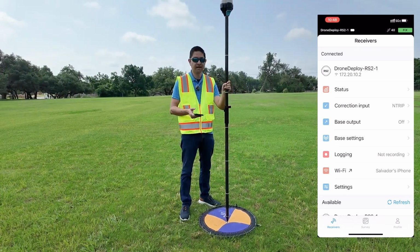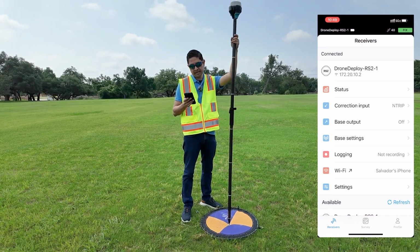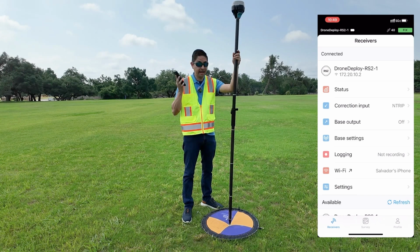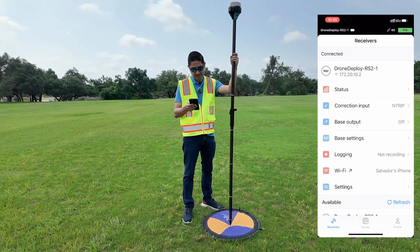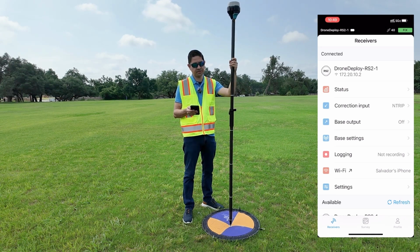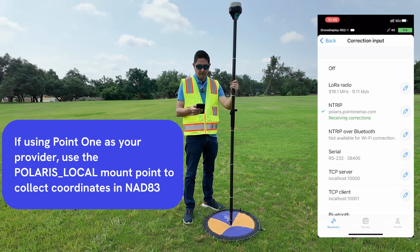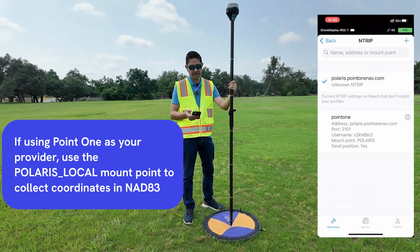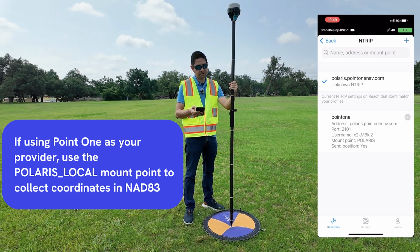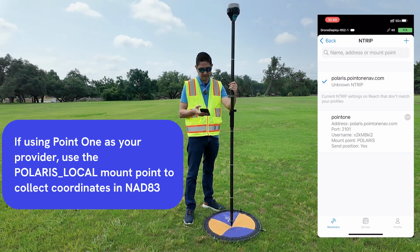of the site. To get the survey in using the Emlid, we need to connect the Emlid to an NTRIP network and a hotspot. In this case, I'm using my device as a hotspot, and I have a connection subscription to a provider that is inputting the correction into the Emlid. Whenever you go and set up that connection, you have to get the credentials from your provider, and they're going to give you a password and a username together with a port number. It's very important to have the correct port number for the area that you're surveying.